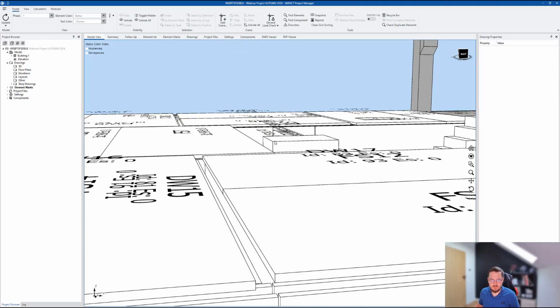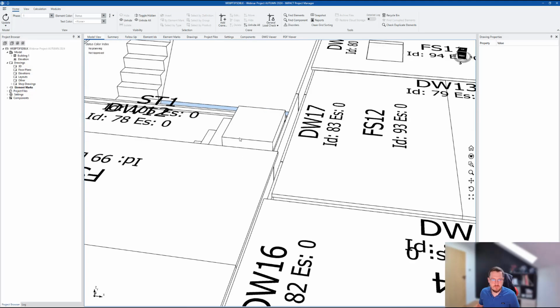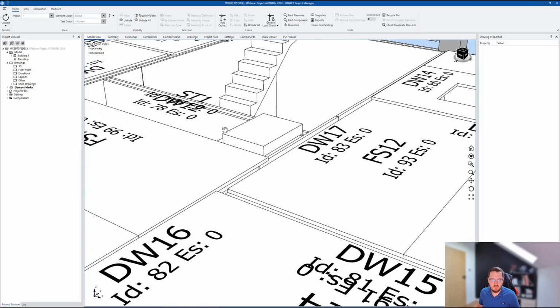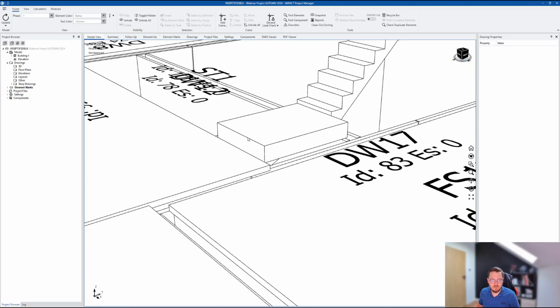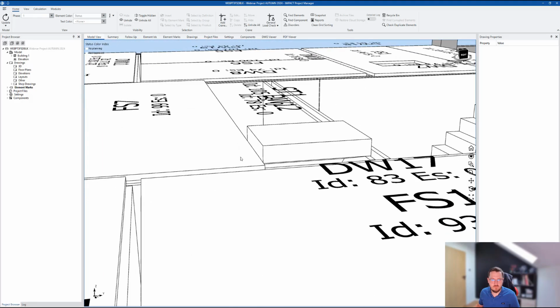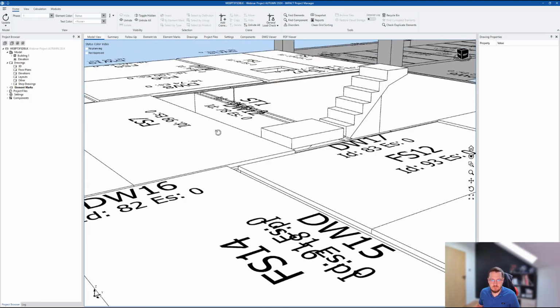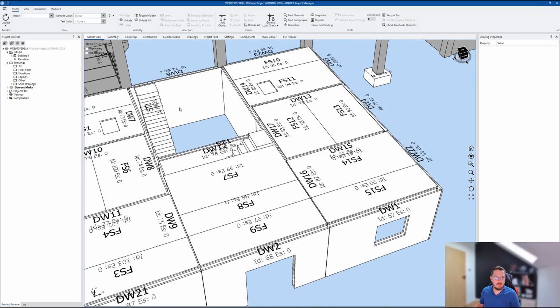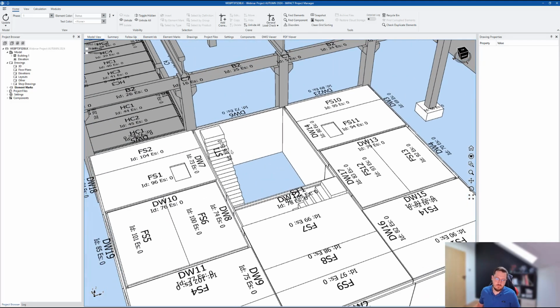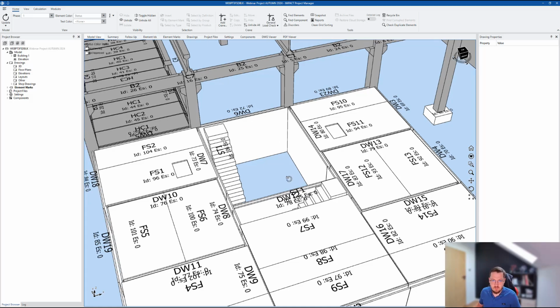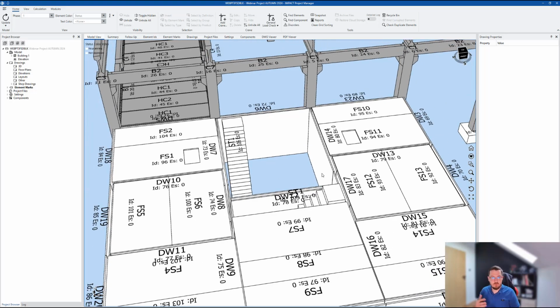That's an error. I probably should have made that 3000 for the top, because the last step was raised. So just a matter of actually that's good, because we still have concrete pour over on that, so my levels are actually good. Okay, so that's good. Here, of course, this is a stairway to nowhere really, so let's not worry too much about that. But yeah, so that's how you create linked elements in terms of stairs.